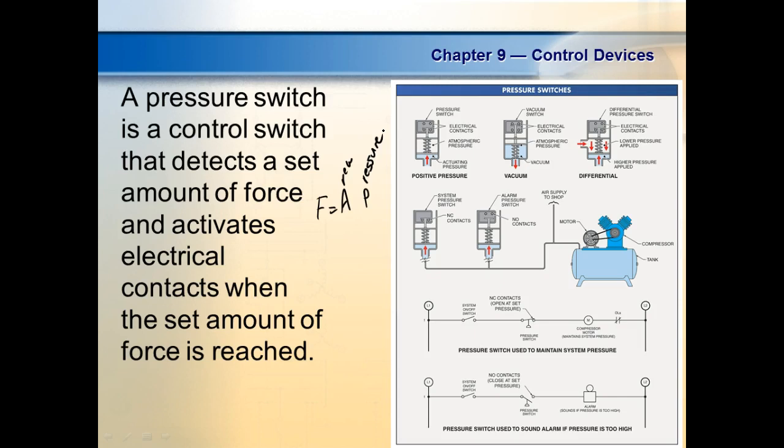What a pressure sensor will do, and like I said, we'll show you all those on the manufacturing line, is indicate if it's above a certain pressure or below a certain pressure. A lot of them have an adjustment on it, so you can set where it goes between a true and a false. And we'll show you all that. So we have all different types of sensors. We got an electronic pressure sensor back there.